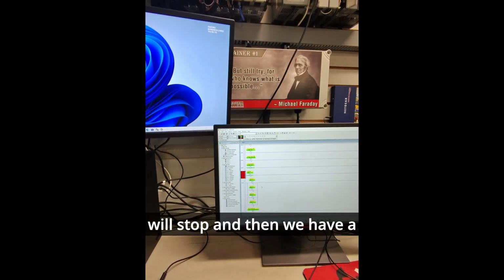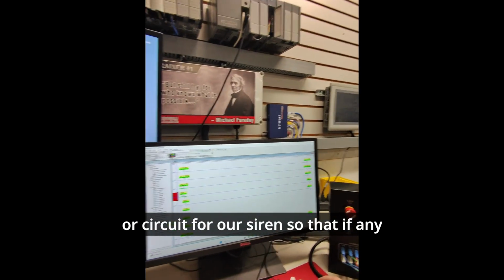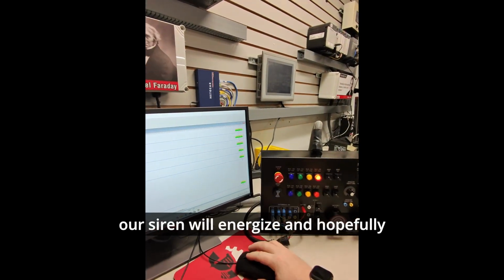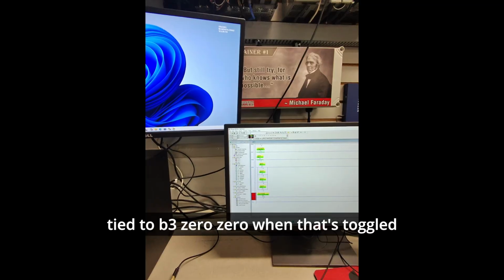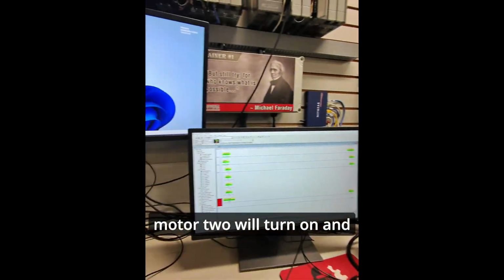And then we have an OR circuit for our siren, so that if any of the single pole, single throw switches are turned on, our siren will energize and hopefully produce a sound. And then lastly, we have an internal bit tied to B3:0. When that's toggled, motor 2 will turn on and spin.